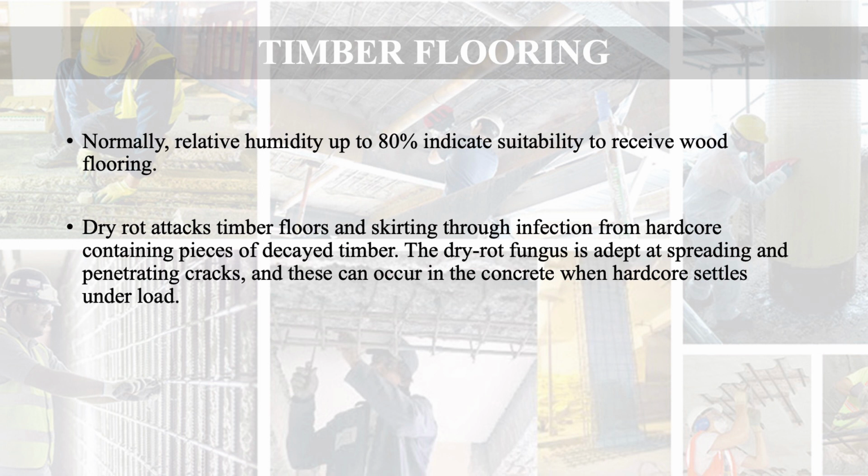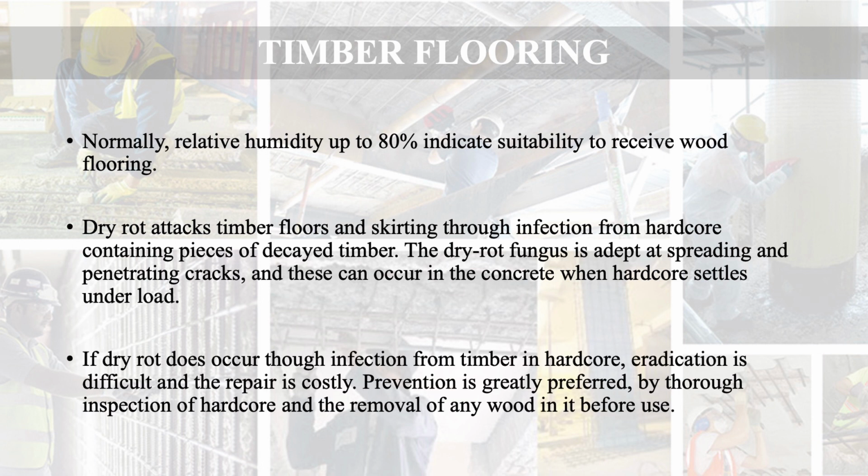hardcore settles under the load. When there is a settlement in the hardcore, then this may occur. If dry rot does occur through infection from timber in hardcore, the condition is difficult and the repair is costly. Prevention is greatly preferred by thorough inspection of hardcore and the removal of any wood in the hardcore before